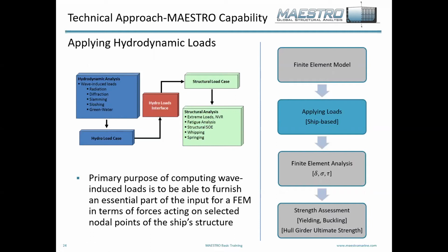When you're running Maestro Wave, and this is one of the more advanced features covered in a separate training, it goes through all of the different potential wave height, modal period, heading, and speed combinations, and evaluates everything to generate all the potential lifetime loads and things.